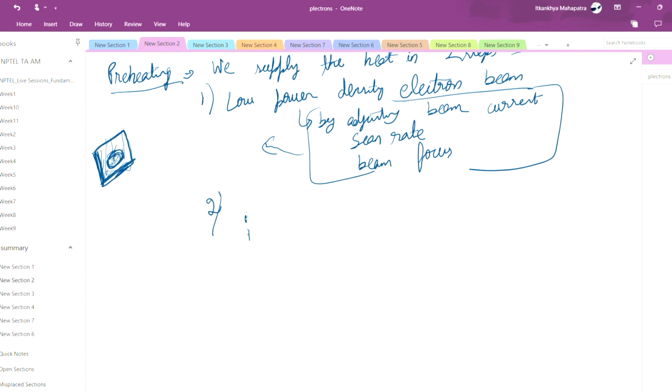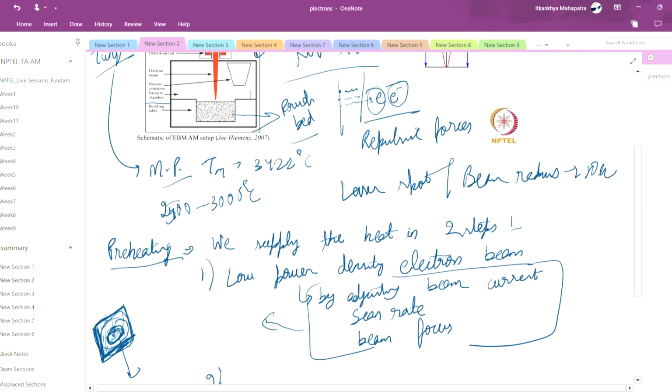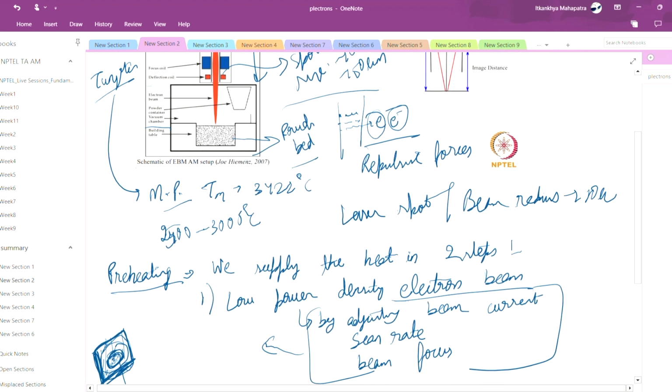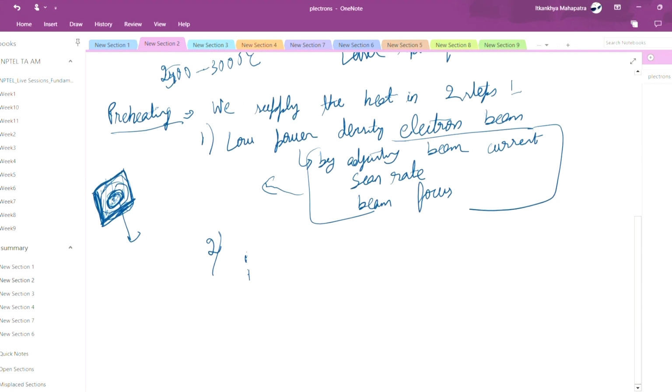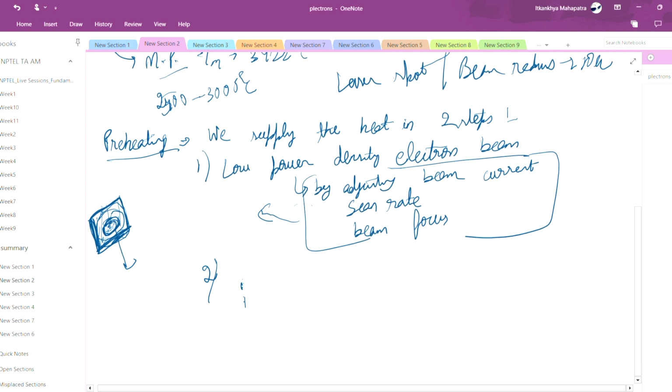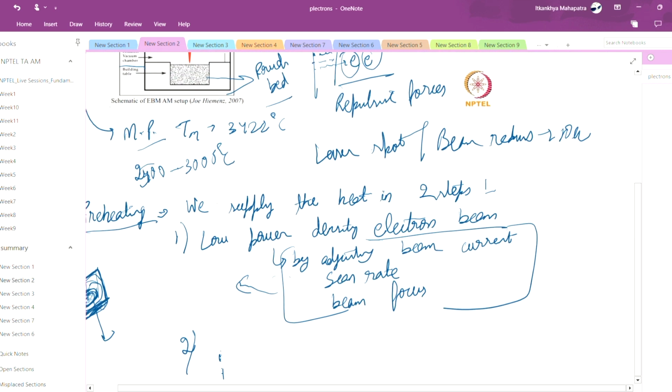Melting should take place only at this portion. If we increase the preheating area, ultimately the whole thing will get sintered. This will make removing the component difficult, and all the powder particles adjacent to the component will be affected. We have to optimize the preheating temperature carefully based on the material, and these parameters help us adjust the preheating temperature.